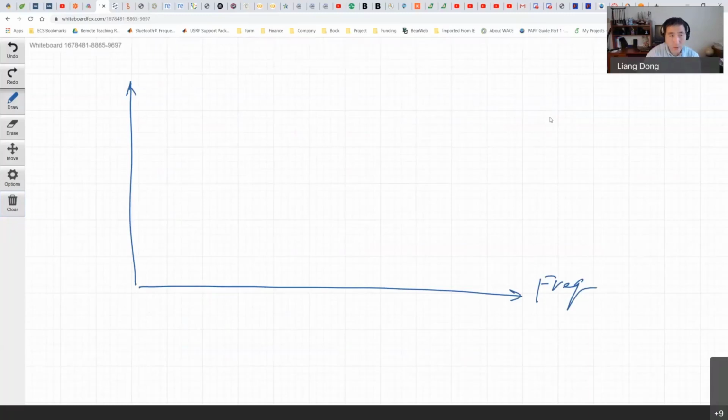Let's look at only the amplitude of these. So that's my absolute value of h omega. We know if you design that FIR filter, that's a linear phase. If it's an IIR filter, it's most likely a nonlinear phase. But let's throw away the phase issues at first. We just look at amplitude. I want to make sure that amplitude is according to our specifications.